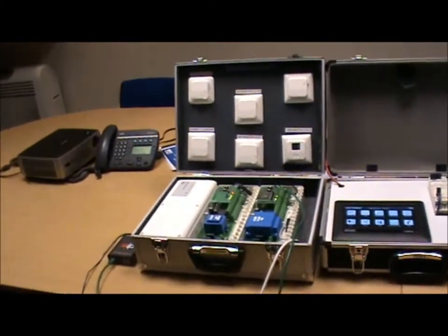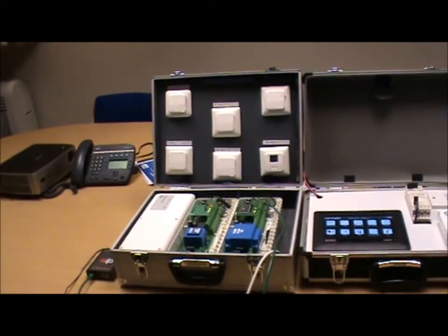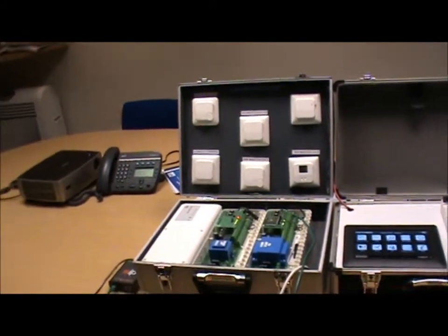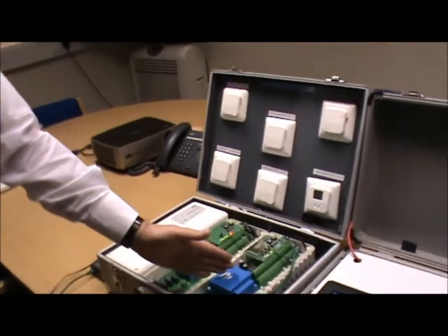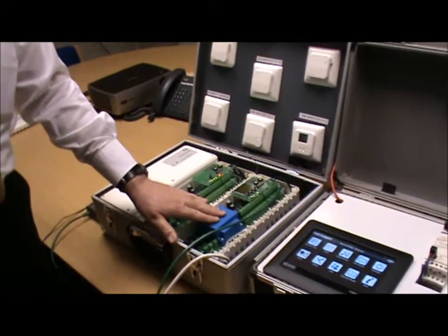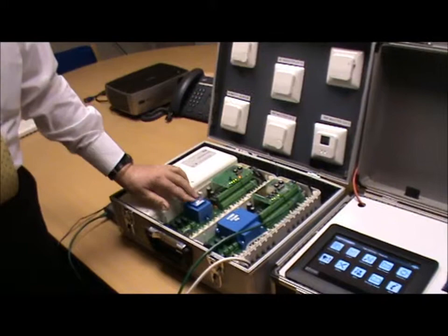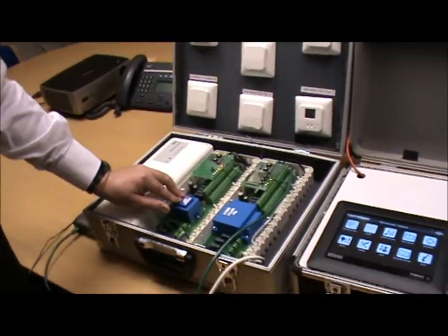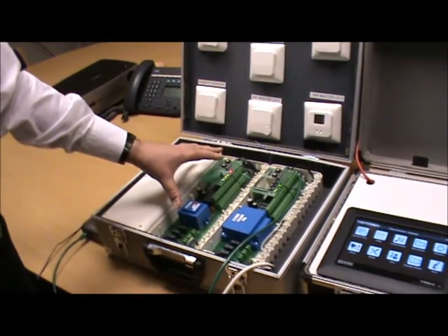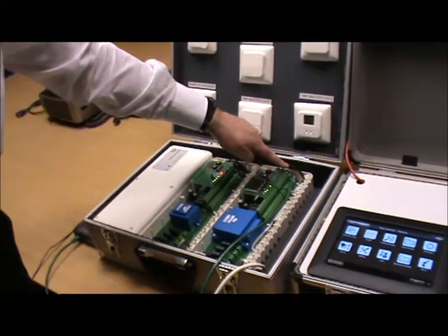Okay, so the left hand side here is the OJ Electronics underfloor heating box, and Patrick will just quickly run through the items that you can see and what they do. On the bottom section here where the green cable connects straight into, this is called the FS BMS module, which is the master, and this is wired and networked through to our standard BA basic master controllers. Generally each of these will be above the top of each individual manifold, and they are networked together using an RJ11 connector.